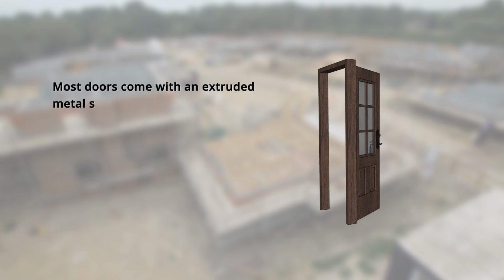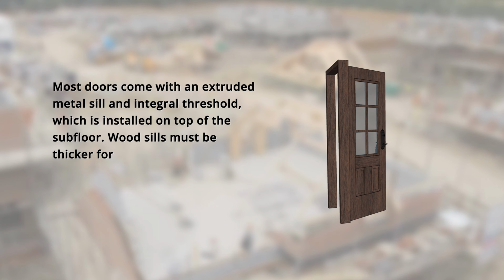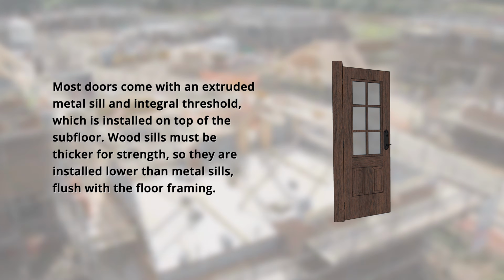Doors. Most doors come with an extruded metal sill and integral threshold, which is installed on top of the subfloor. Wood sills must be thicker for strength, so they are installed lower than metal sills, flush with the floor framing. Let's reference this detailed illustration here on the right.